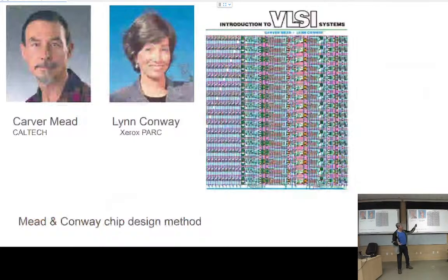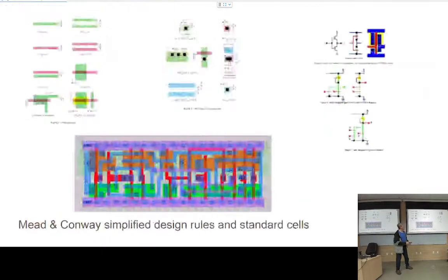And they wrote a book, Introduction to VLSI Systems, that introduced several things that are the basis of how we design chips. Their idea was, instead of having specialized people who knew the transistor in every little curve, what if I have a system designer designing their own chip? So they created something they called stick figures. You just show how you want to connect your transistors together without worrying about the details. They also created the scalable design rules.